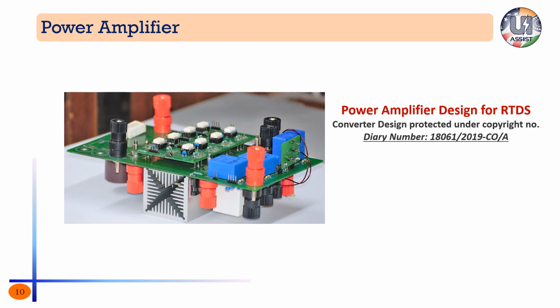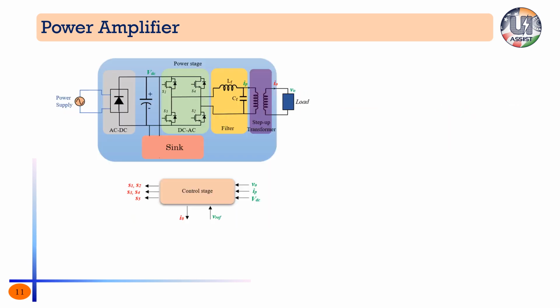So now coming to the next part of this interface, that is the power amplifier. As you can see, this is the power amplifier that is developed and tested here at IIT Kanpur. I'll cover its working. It is developed from a simple VSI topology. And as you can see, the control gives the VREF signal, and the MA of this particular inverter is controlled by this VREF, which is coming from the RT side. And this output current in the load is sensed and sent back to the RT simulator for PHIL simulation.